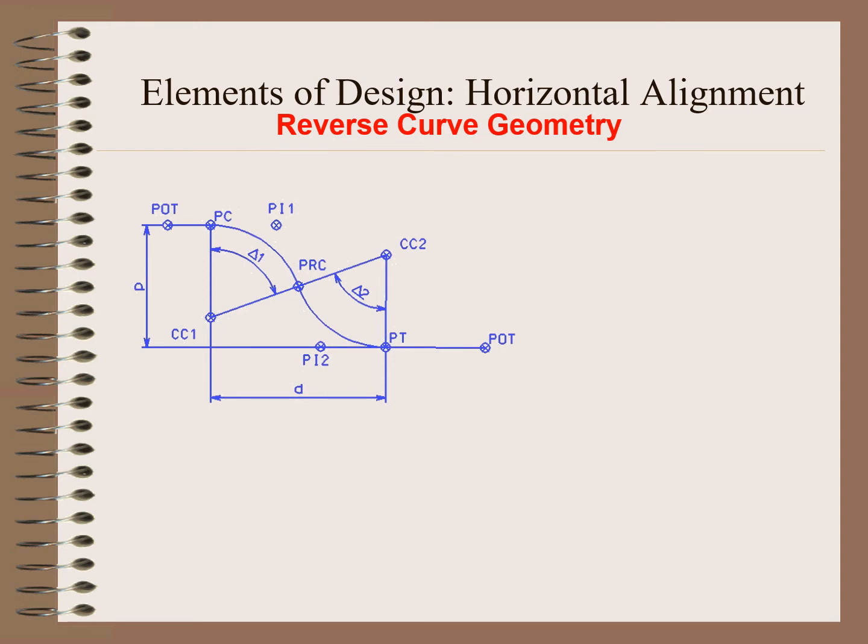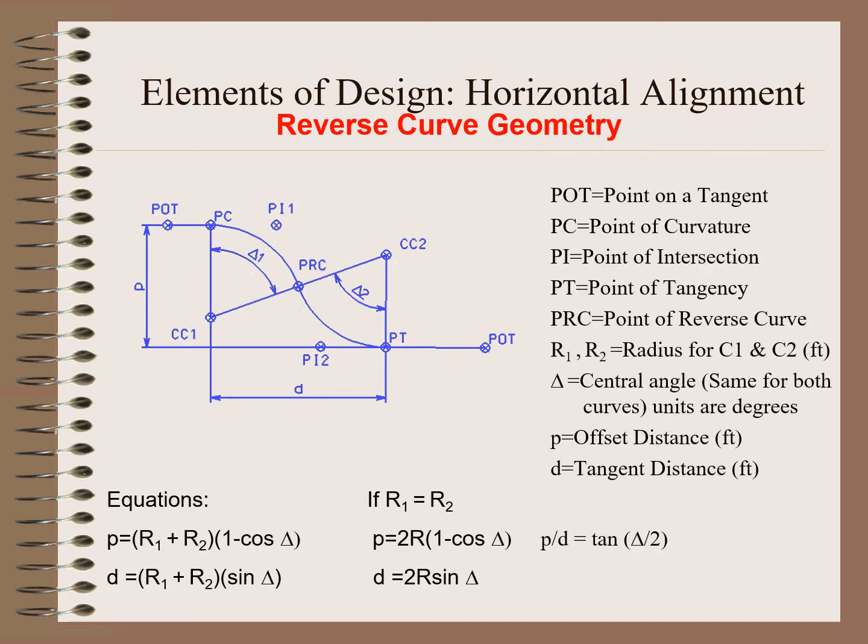Let's review the reverse curve geometry. Basically, in a reverse curve, you have two simple curves back to back, kind of creating an S. So you will also hear it referred to as an S curve. And basically they share one common point.